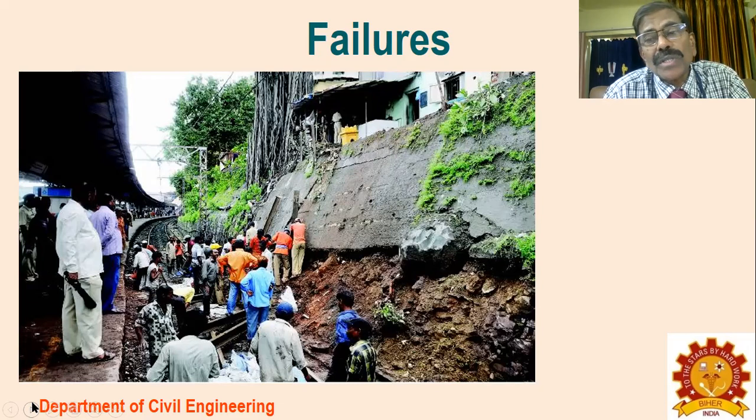So it's a progressive collapse that you come across when some part of the soil fails and the other part of the structure, even though it retains, is at a critical stage of stresses, then the failure will continue. You call it a progressive failure, which can also be initiated because of poor estimation of the soil capacity.